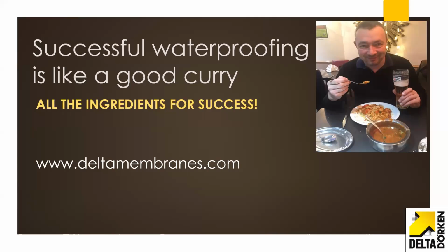Absolutely fine. I'm wondering, from Keith Gold: are we still allowed to sandwich the waterproofing between the external insulation and the concrete? And in your opinion, what is the best insulation to put externally under basement floors or a raft? Yes, you are. That's not sandwich waterproofing. Putting insulation on the outside of the structure and then putting a layer of insulation in front of the waterproofing is perfectly fine, because that's positively pressured.